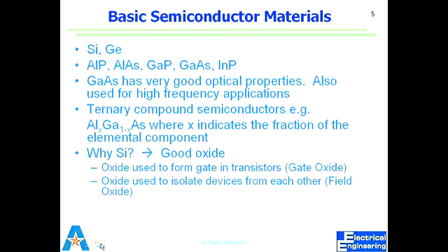So these are major uses of silicon dioxide. Two most important uses: gate, which is, I drew that transistor last time. There was this part where you had to have an insulator layer and you apply some voltage on top of that, which results in accumulation of charges which connect source and drain. So there is a path of travel. That is where we want to use oxide called gate oxide. And in other words, field oxide, where we want to isolate electrically active devices from each other.